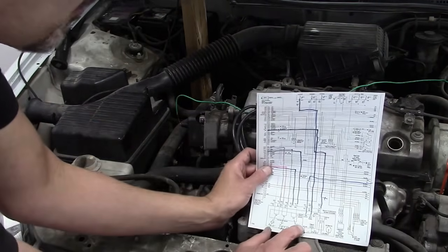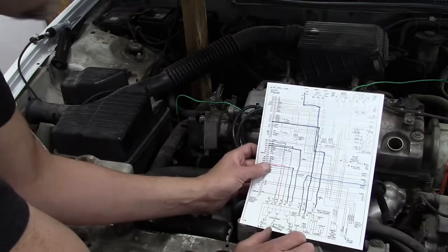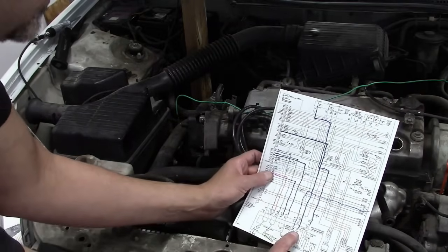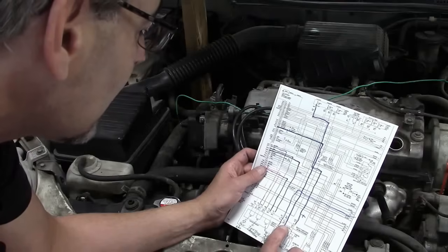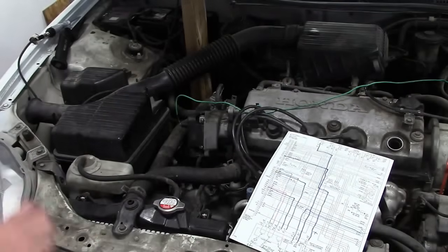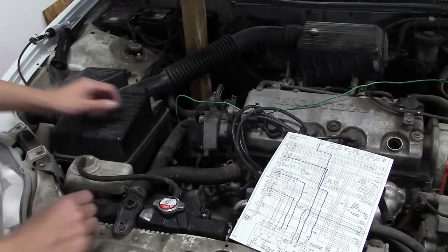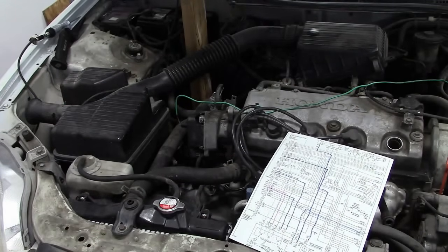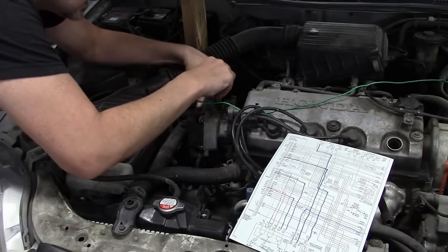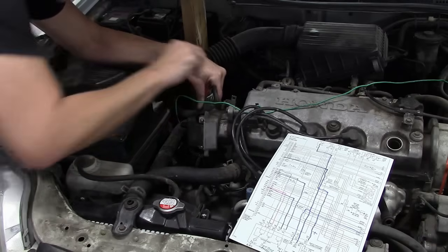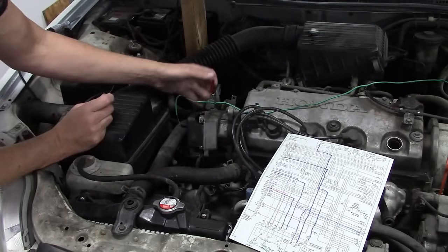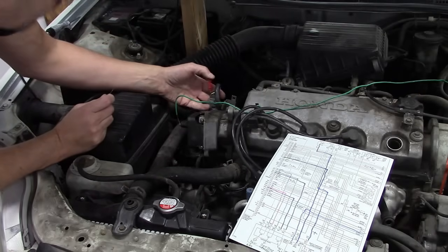I can see it on my wiring diagram. I can also see it on my dry erase board a lot clearer than I can here. And let's just see here. Yep, yellow and green. So there is definitely a yellow and green wire right there. Let me get a back probe. It is yellow and green. And if I put low amperage to that, I could just use my test light.